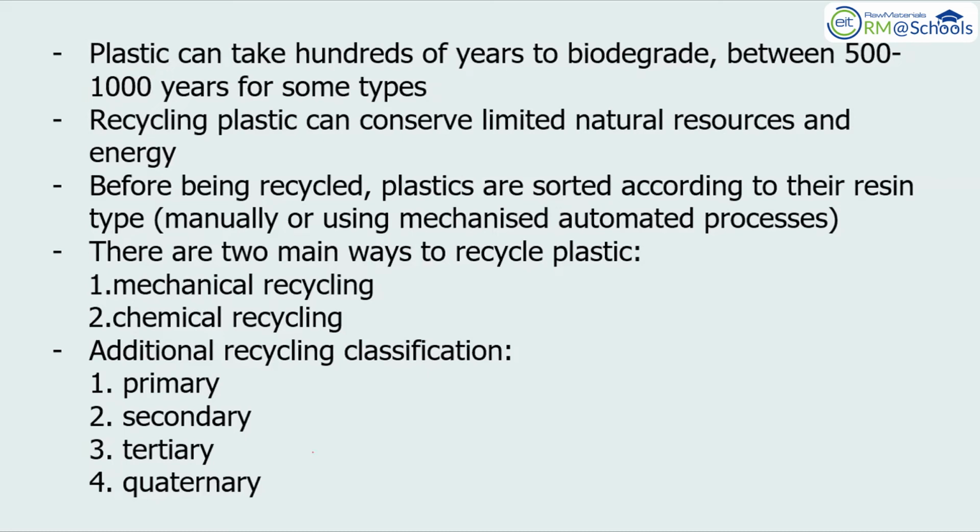We have mechanical recycling. In mechanical recycling, plastic waste is first sorted by material type, and then is milled and washed, passes a flotation separation, and it's finally dried. And we have chemical recycling. Chemical recycling is any process by which a polymer is chemically reduced to its original monomer form so that it can eventually be processed and remade into new plastic materials that go on to be new plastic products.